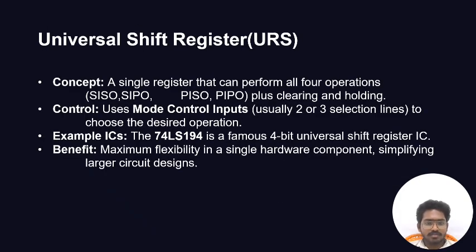And then there is another shift register called the universal shift register. To maximize flexibility, we have the universal shift registers. A single sophisticated IC is designed to perform all four operations we discussed above, plus functions like clearing and holding the data.